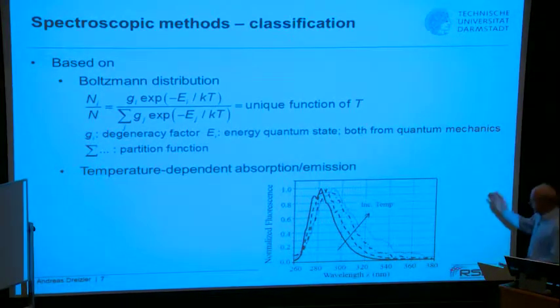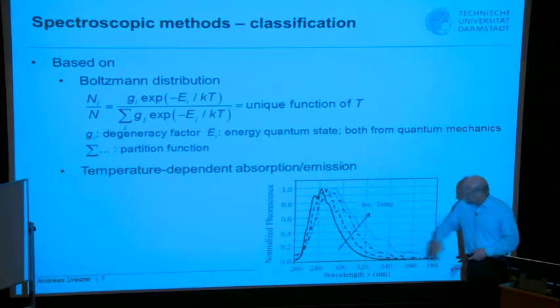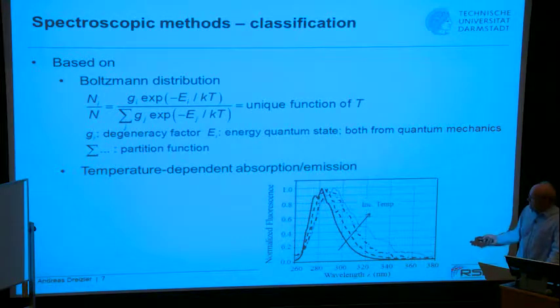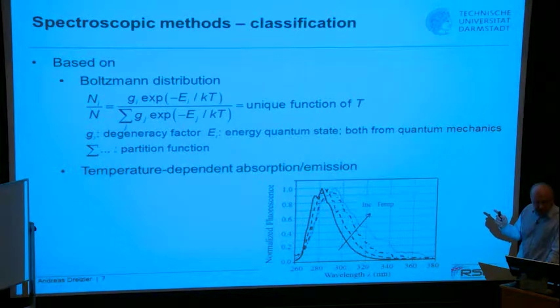The next class was about the temperature-dependent absorption or emission. So the idea shown here for the emission, in this case it's toluene, a tracer molecule, we go into more detail into that, is typically seeded to the flow. What you see here, after this is normalized, is that if you excite these molecules, then for increasing temperature, the emission band, here are the wavelengths, here the normalized fluorescence, is shifted further to the red. And this information can be decoded, after calibration, I have to say, to temperature.